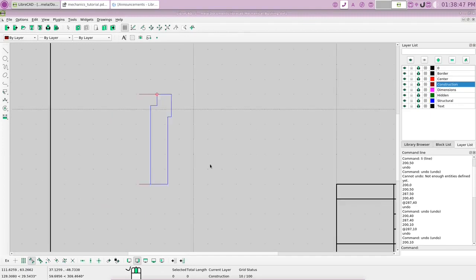Okay, let's go out a little bit here, zoom out by rolling the mouse, the center mouse button. Let's switch to the center line layer. And let's select 2-point line, and snap on end, and let's snap here. And let's snap here. Okay, right mouse click to get rid of that. Now you have a center line. But we want to extend that center line.